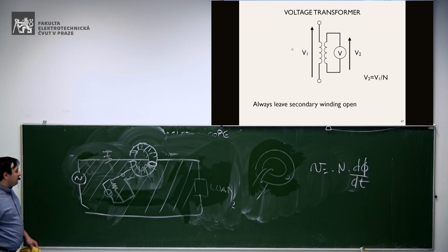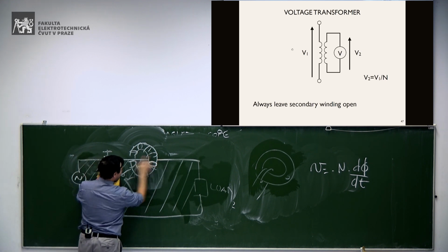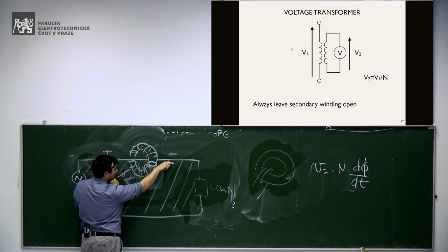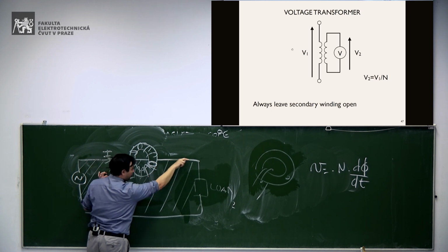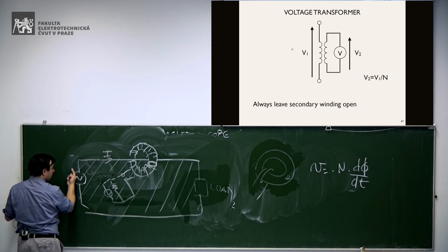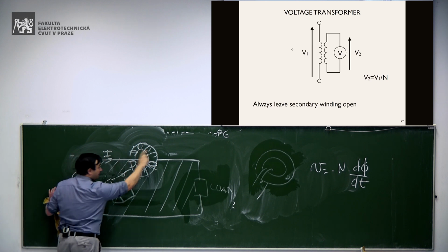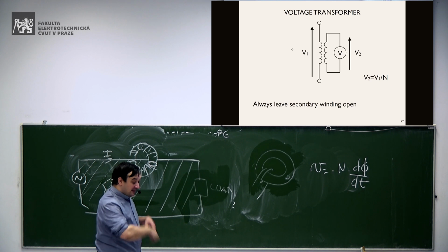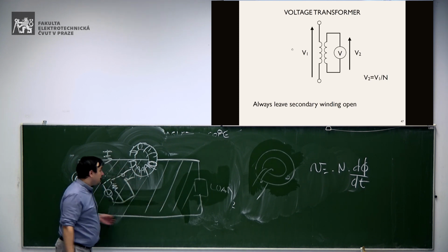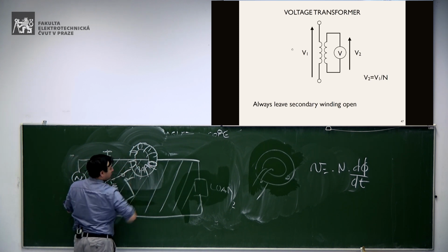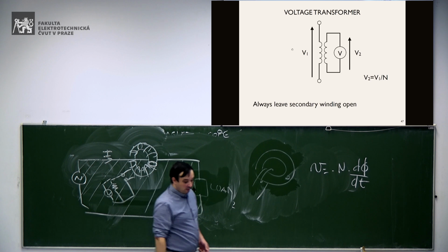This is the turn. Even if you don't see it, typically you see only this portion. So you see only one wire which enters in a toroid. And you think, okay, where is the turn? Well, watch where the wire goes. Goes to the load, goes back to the generator, and returns here. Eventually it must close, because if it doesn't close, there is no current. So if there is a current, the circuit will close somewhere, and if it closes, it means there is a ring, which is a turn which includes a portion of the toroid inside, okay? So always be careful about that.